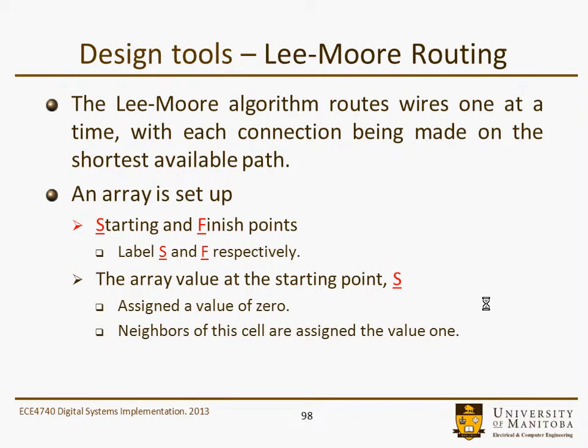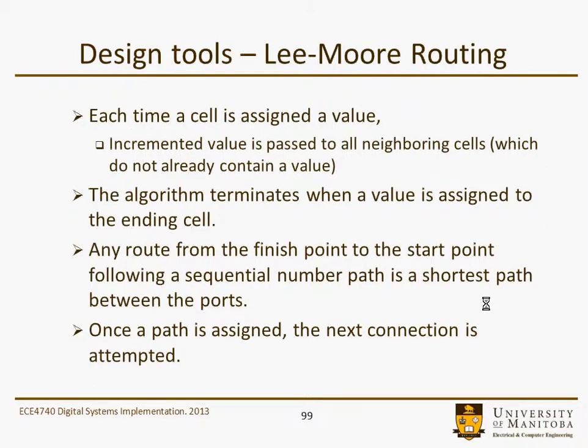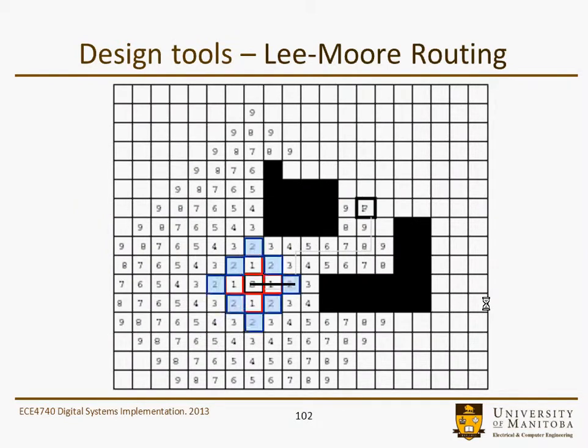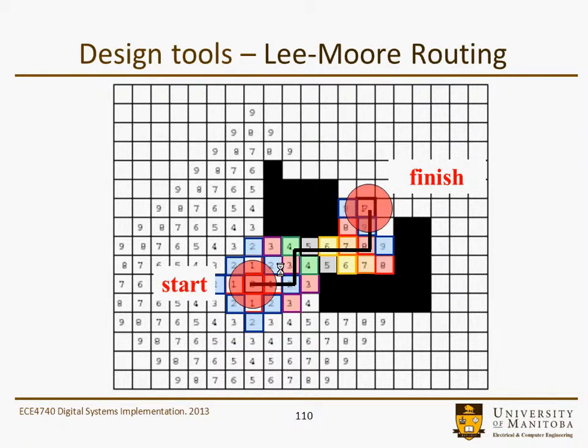And here's an example of a simple Lee-Moore routing algorithm. It's very old, and really it's just to point out that other techniques might be useful at some point in time. This is just a breadth first search from a source to a destination, and it's illustrated here. I sort of ran out of steam with the colors. This would still be all those that are 3 hops away, 4 hops away, 5, 6, 7, 8, 9, and you get a route from start to finish, and you avoided areas that you weren't able to route on.